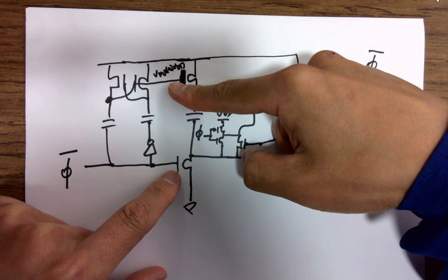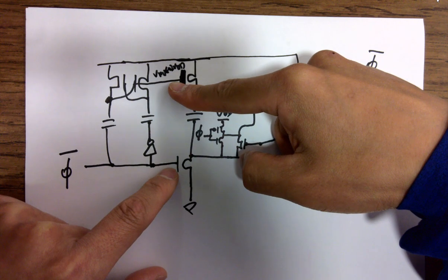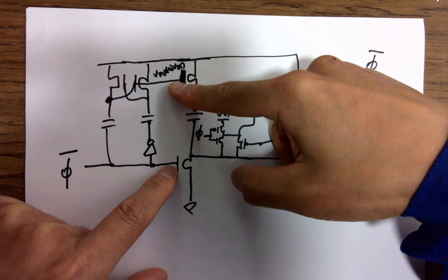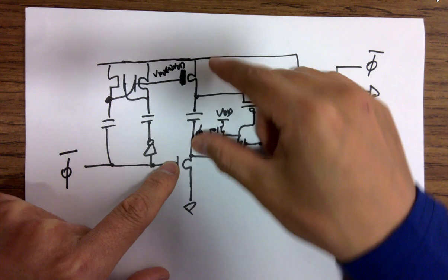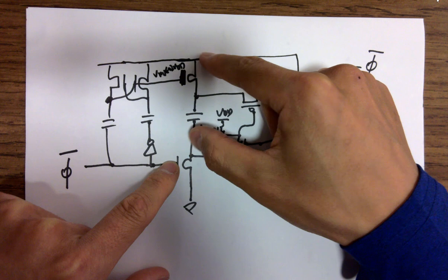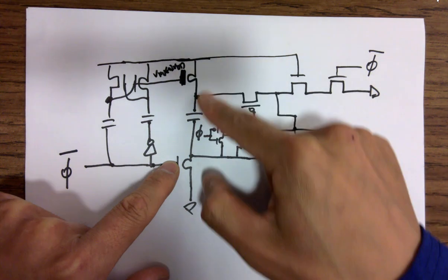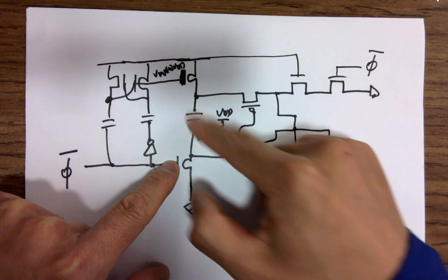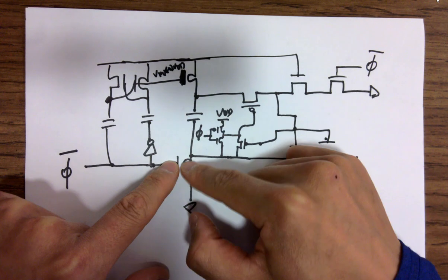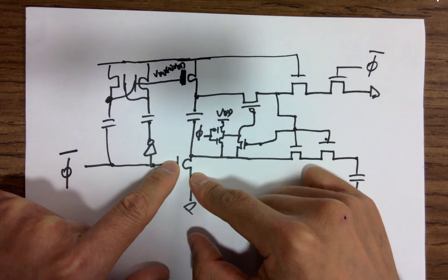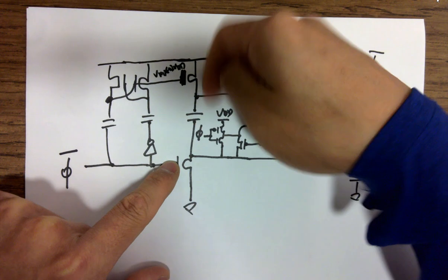It's a falling edge. It's off, right? If it's off, which means there's no channel to go to the ground, so it's not able to pull anything, right? Even though this is on, it's okay. There's no falling edge, so it's not pulling anything. All right, so there won't be any current going through the cap.